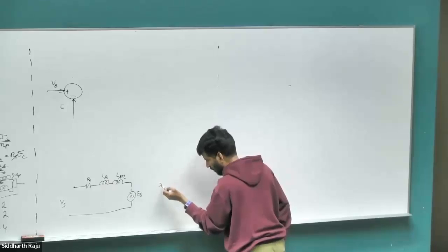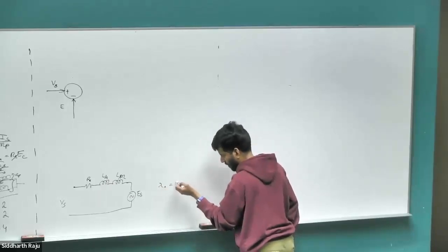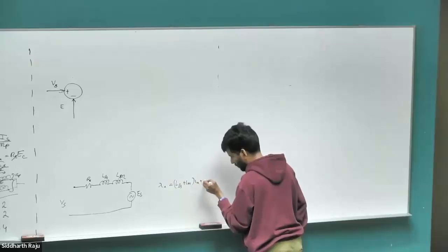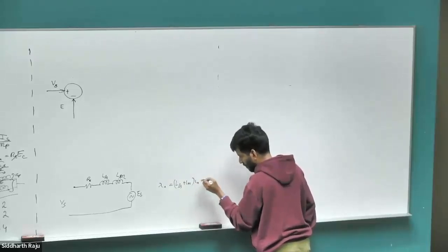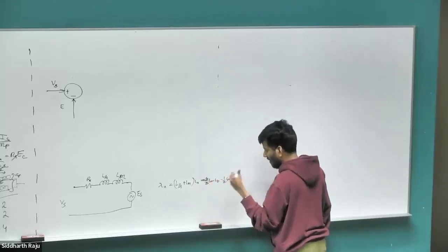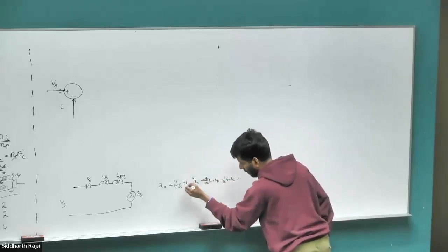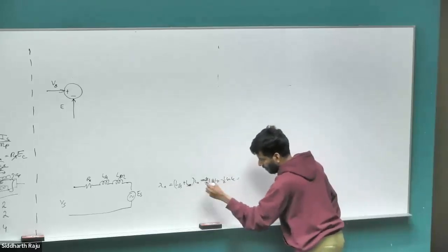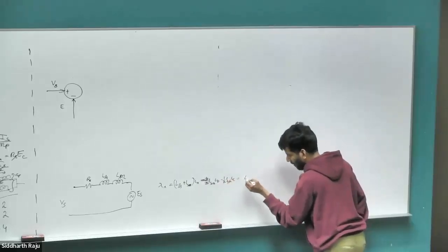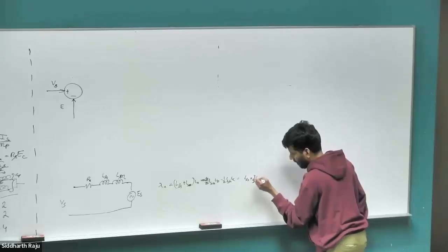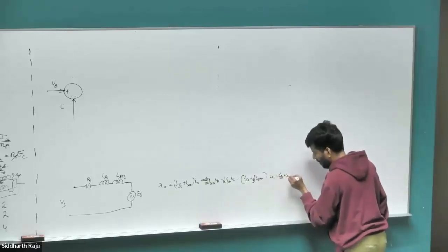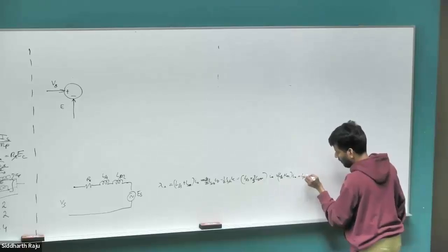Again, in lecture 25, I think, we derived this expression where this one is LS plus LM times IA minus 1 by 2 LM IB minus 1 by 2 LM IC, which ended up, sorry, there was a big mistake, L self, which ended up coming out to be LLS plus 3 by 2 L self times IA, which was the same as LLS plus LM times IA, which is LS times IA.